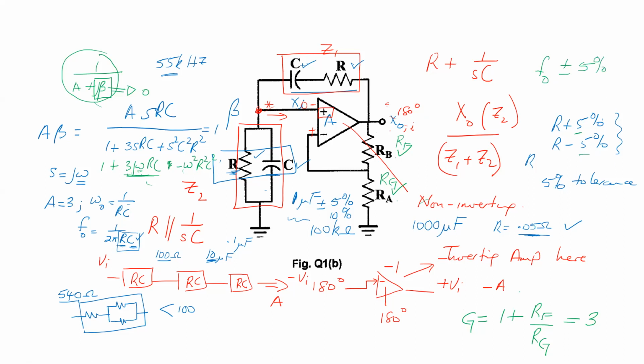So it's very unlikely that if you design this for 55 kilohertz and you actually breadboard it, when you measure it with a scope you're going to get 55 kilohertz, you're not, right? You'll get somewhere, it might be a little bit above, it might be a little bit below. And the explanation, of course, is the tolerance fit.